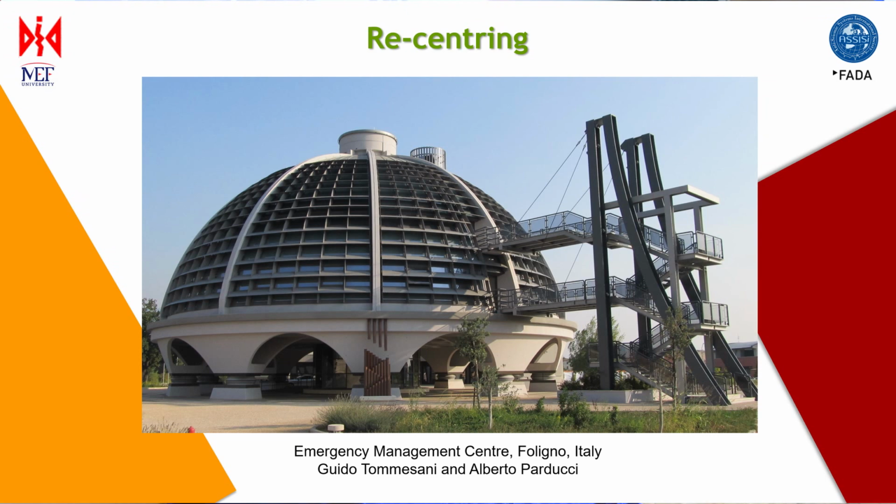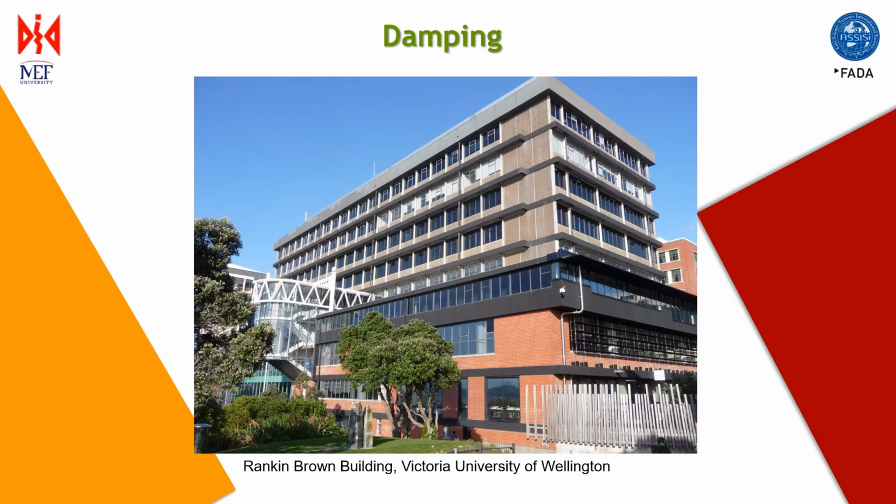A recentering or restoring force keeps bringing the superstructure back to its original position while preventing motion during wind gusts. Damping lessens the relative horizontal movement between the superstructure and foundation, reducing the cost of bearings and other details. It is important the width of the gaps that accommodate the movement.